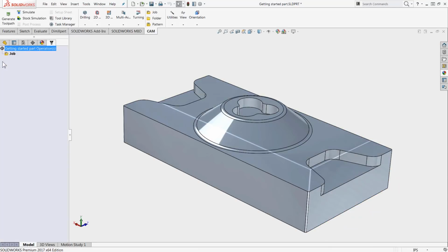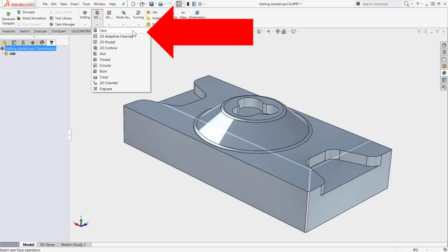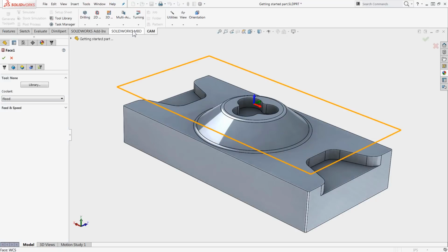Now for this, we'll pick between standard 2-axis and 3-axis toolpath. I will start with a standard facing. This will establish a flat datum on top of our part, and I think generally most CNC programmers will start with this. Now, one thing that is important that I point out is that you will see the menus are going to be the same no matter what toolpath we pick.